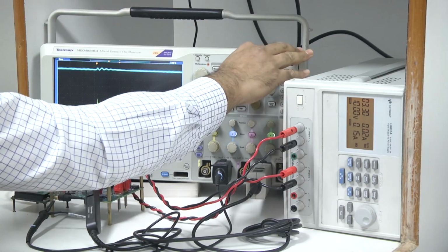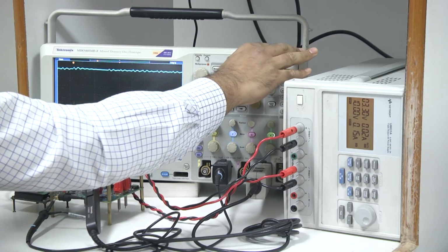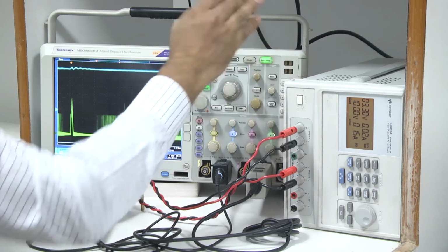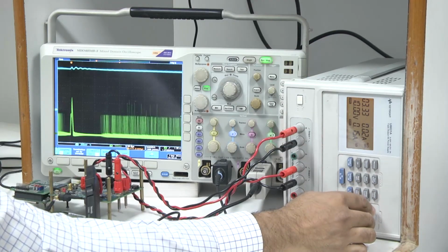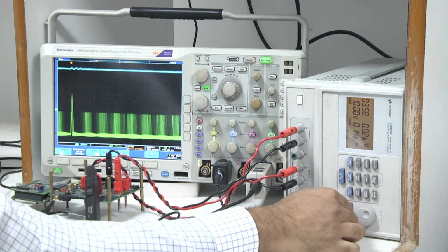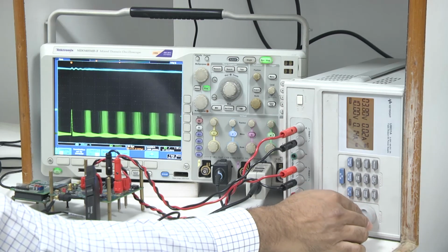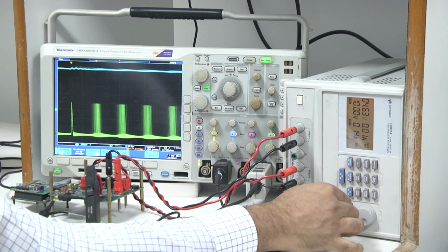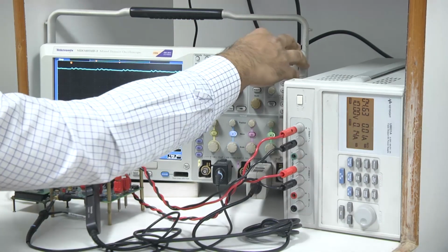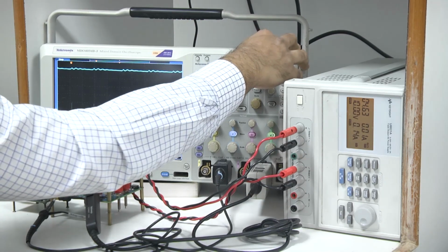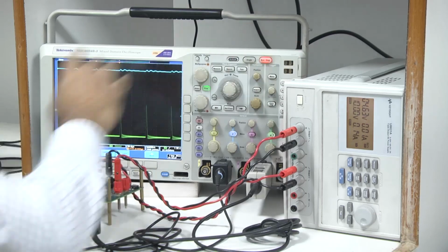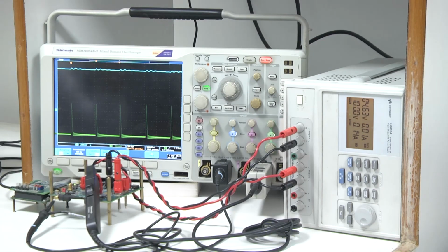Now if we increase this input voltage, that means instead of 3.3 volt, you see, when the on pulse is sufficiently large, the occurrence of such high pulses goes down. These pulses are not coming, and you are getting more or less PFM operation. But what is happening? The peak current has increased because your on time is fixed and the input voltage is increasing.